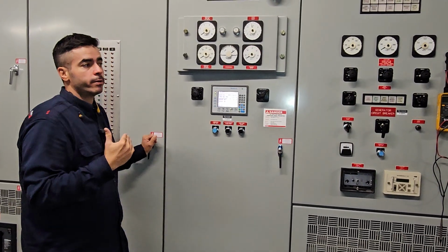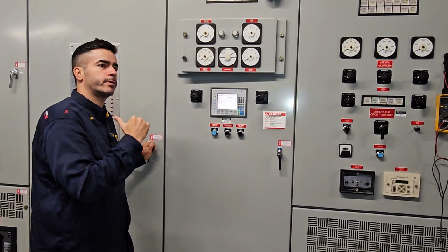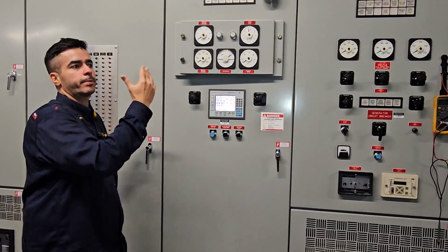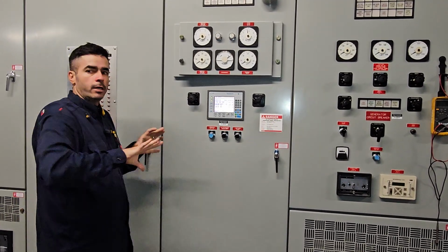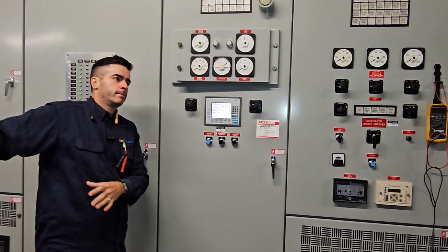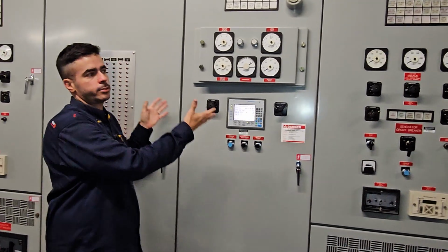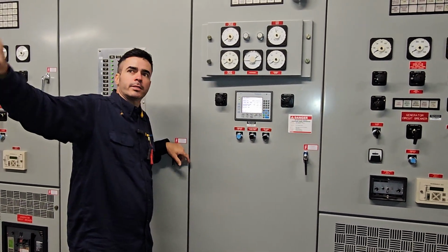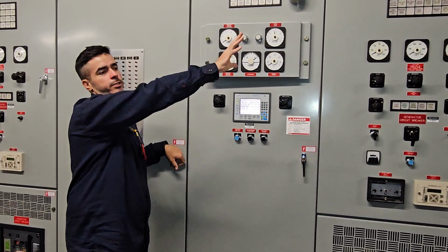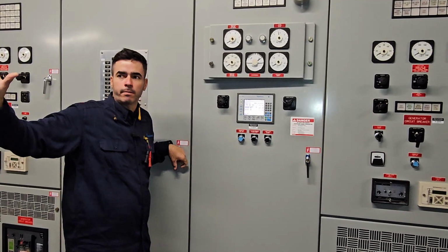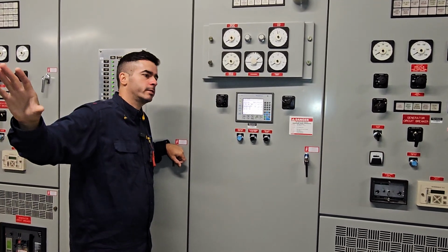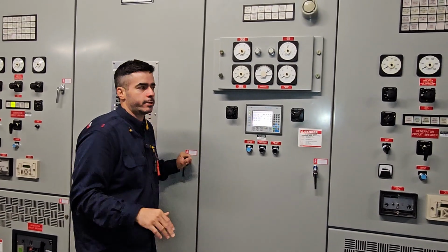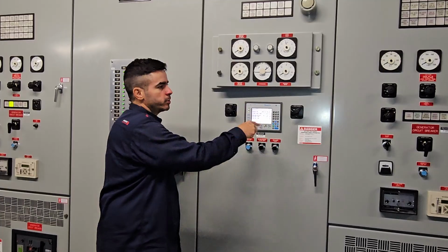But we have lower priorities, like for equipment branches, priority 2, priority 3. If we are in an overload condition and don't have enough capacity, the system will say, okay, I'm gonna get this load out of the bus because I don't have enough capacity. I have 1,000 kW and I need to provide 1,200. So this ATS, which is for the chiller 2, I'm gonna kick it out. I don't care about the load, it's the lowest priority, because I don't have enough capacity, or I'm gonna lose the generator and then I'm gonna be in the dark, right? So we have some set points for that.